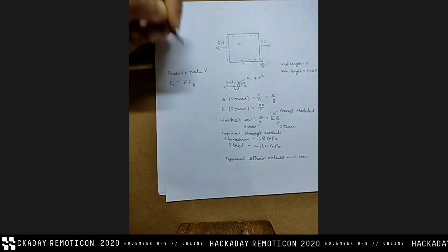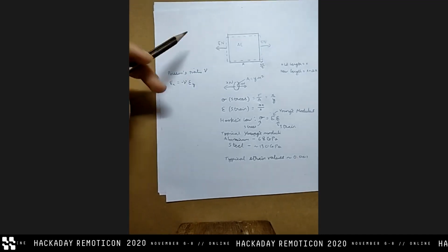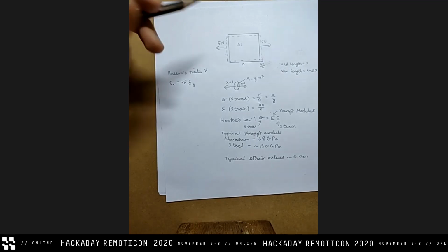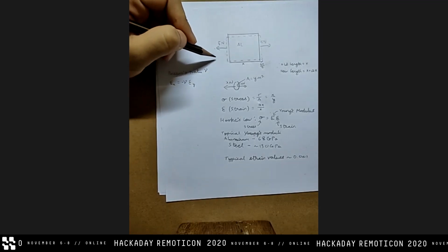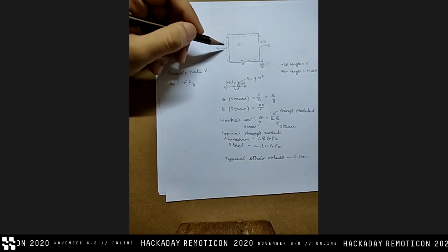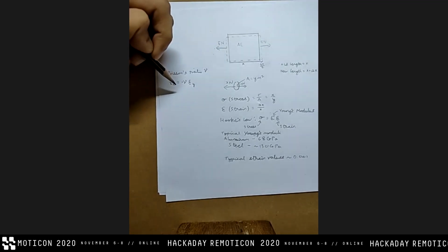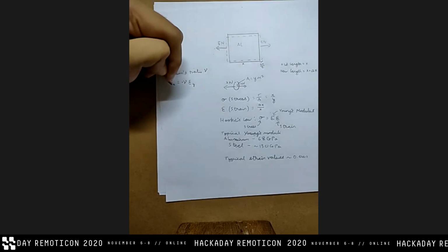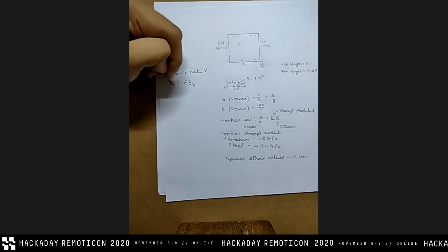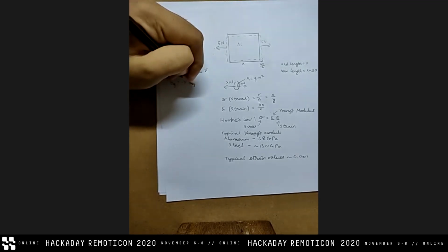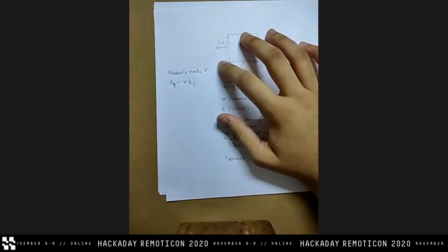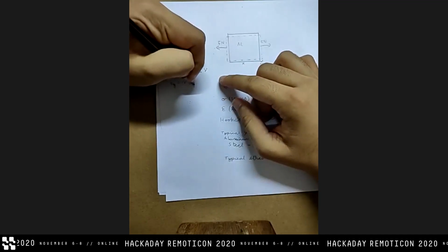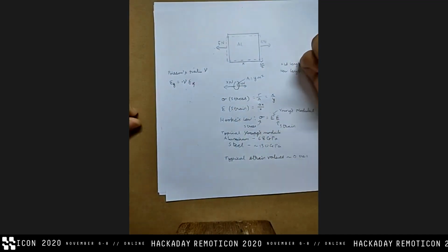the y direction. So this allows us to go to three-dimensional cases, because now you know that this force here gives you a certain strain in the x direction, and you can use your Poisson's ratio to find the strain in the y direction. So in this case, because you want to know y, it would be like this instead, where you're taking the known one and using it to find the unknown.